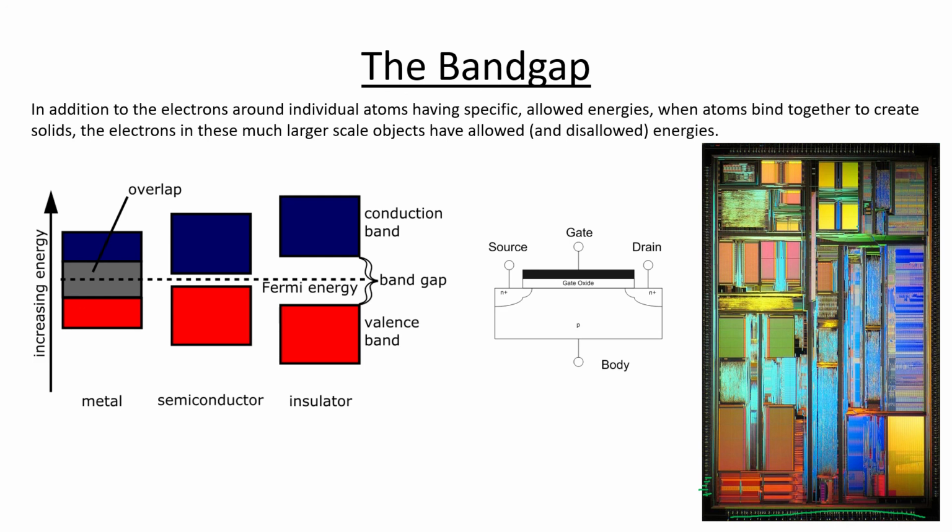I mean, this is from the late 90s, so this is probably maybe 100 million transistors on this chip here, on this chip that I'm talking about, in case you're not seeing my pointer. These days, you've got billions and billions and billions of them because they've managed to make these transistors extremely small. I think the latest technology has the smallest dimension of these transistors being something like 7 nanometers, so 7 billionths of a meter. And to give you a sense of scale, and one I think I've used in the class before, a human hair is like 50 to 100 millionths of a meter in diameter.